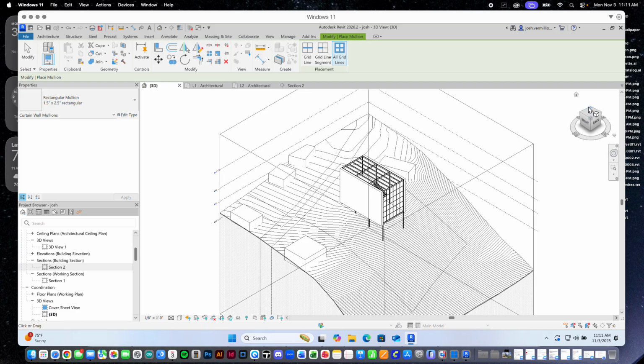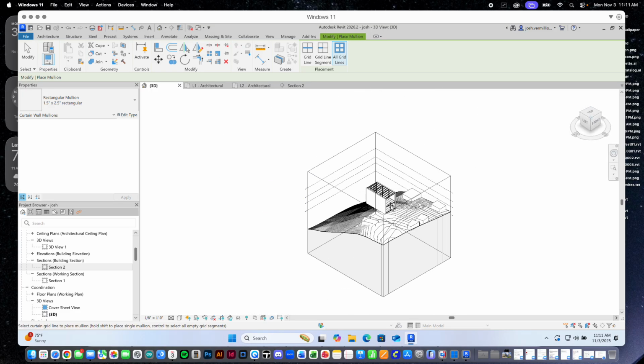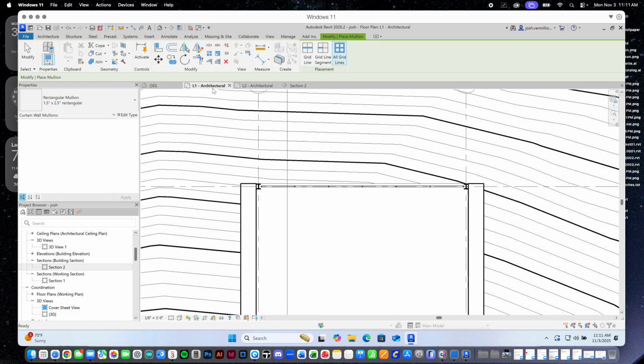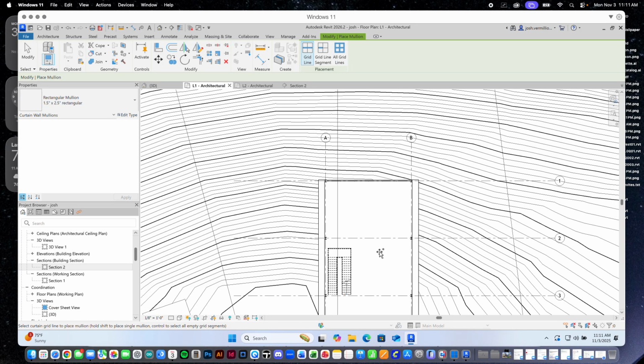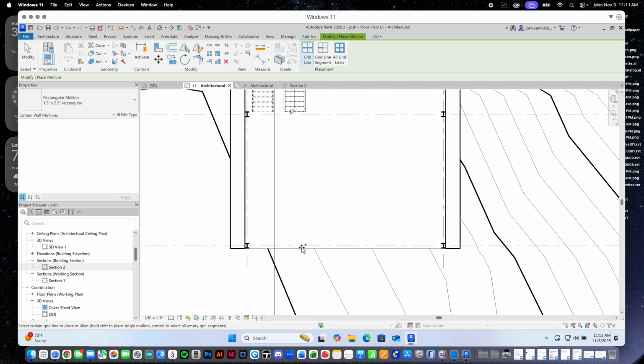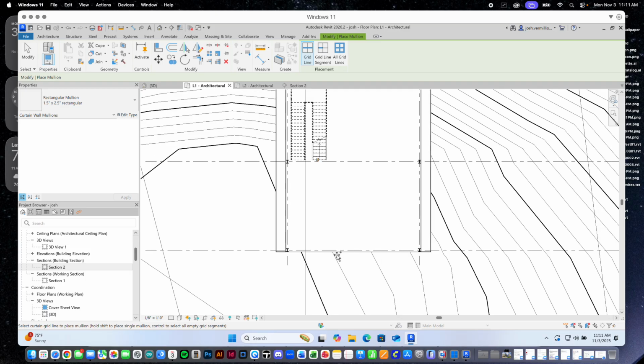Let's go around now. Let's turn this 180. There we are. All right. Look at that three-dimensional view for a moment. I'm going to do mostly the same thing. Go to level 1. Now, instead of looking at the north side, I'm going to look at the south side. Later on, we'll start to expand glass and start to cantilever some things out. We'll build a bridge from the south, from the entrance all the way down to the road, etc. We'll do that stuff over the next week or two. But let's just figure out this curtain wall.